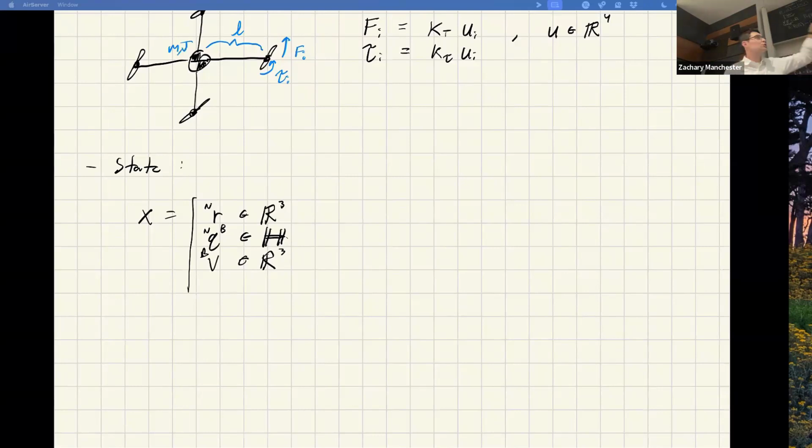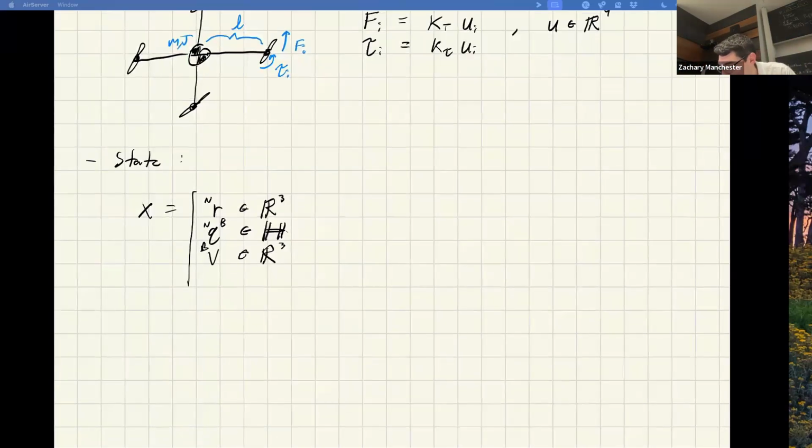So there's some subtlety in choosing these frames, but the upshot is if you do it this way, the message is: put everything in the body frame as often as possible, and it works better. And then obviously the angular velocity in the body frame as well. Like to your point, that's where the IMU is, right? Our errors are measured in the body frame, and the actuators are bolted to the body frame. So you'll want it in the body frame. And this guy is R3.